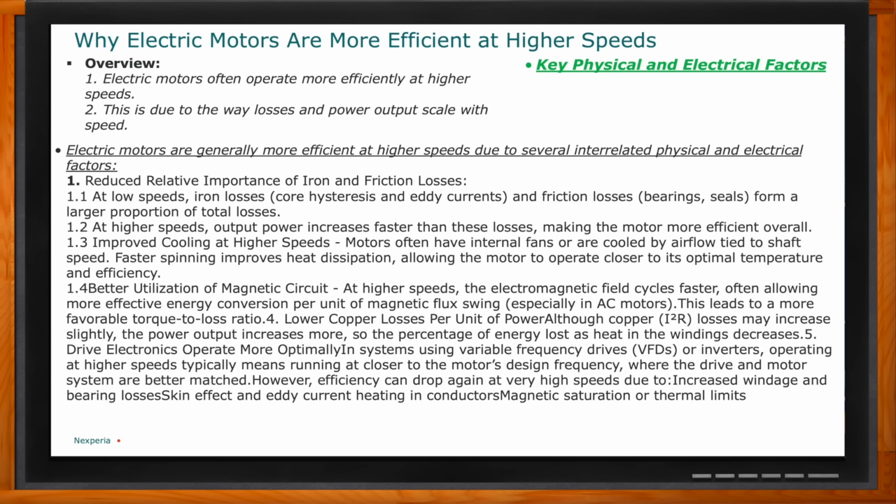When we work with the designers and find that design point that's optimal, that reduces electrical mismatch. We work with a system, and an MCU actually takes care of it as well. It can be programmed to find the optimal minimum and maximum speed of that envelope of the motor. The high speed limitations, of course, are the windage and the bearing drag, and that's why they go into ceramic bearings now, which is kind of nice. The conductor skin effect and the eddy currents, and they go into multi-stranded wire. Of course, the saturation and thermal limits.